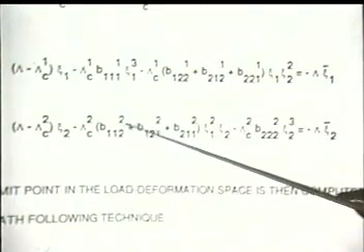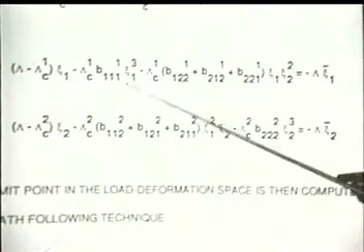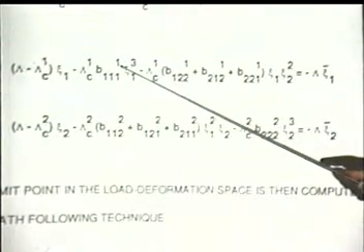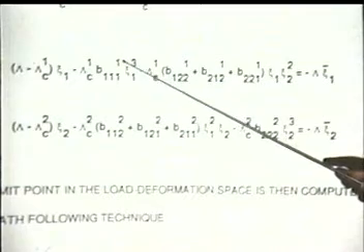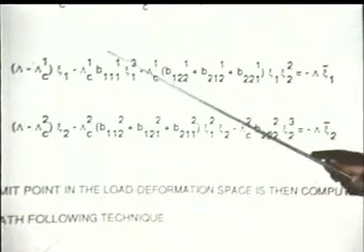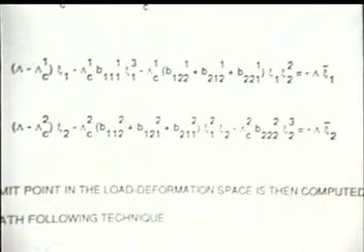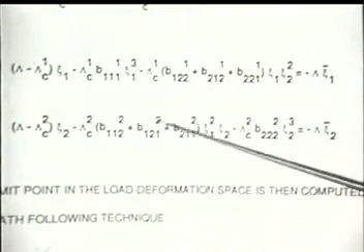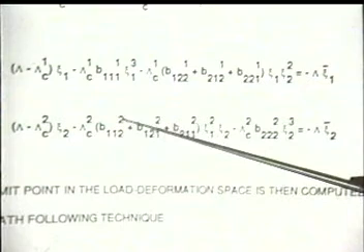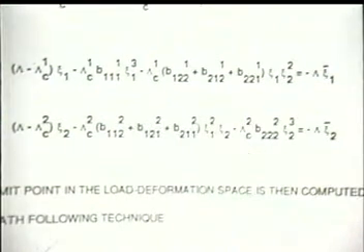The superscript 2 here doesn't mean that it is squared. Remember, we have an uppercase index which designates whether it belongs to the first buckling mode or to the second buckling mode. Maybe one should put that into parentheses, but there is not much doubt what that is. It is not squared.